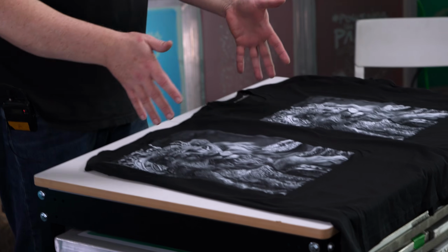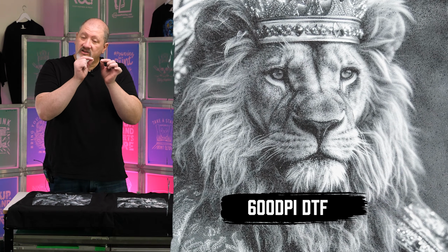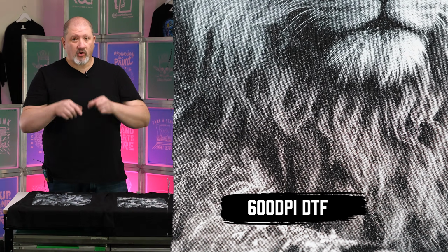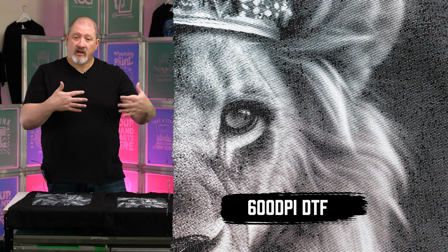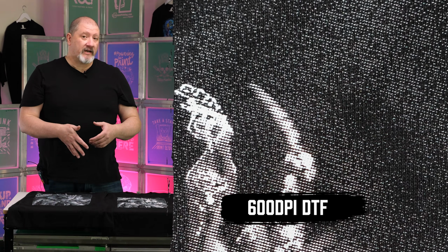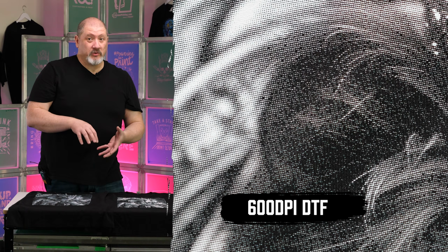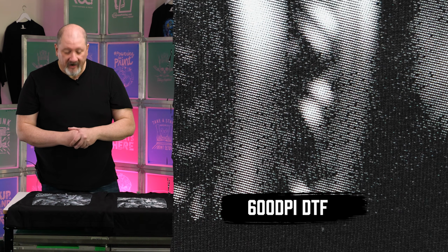Would I do this again? I'd only do this on small scale. What I learned from this is, again, as that print head travels over the film, it creates a little bit of an atmosphere on the film. So because they have dots so close to each other, when that powder hits it and then melts, stuff is so close together that it can end up becoming a little bit of a solid sheet in some of those areas with that adhesive. And multiple presses, even with textured fabrics, don't quite push that hot melt powder into the shirt. But I would definitely do it again for a smaller print run. A challenge to get it all to transfer correctly.